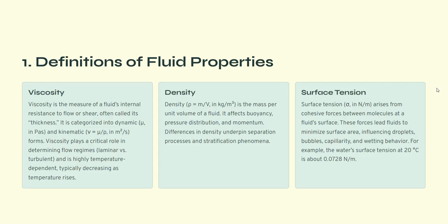So first of all, I'll go through the definition and importance. Viscosity is the measure of a fluid's internal resistance to flow. The higher the viscosity, the harder it is to pump it. It's highly temperature dependent. For example, oil becomes less viscous when heated.